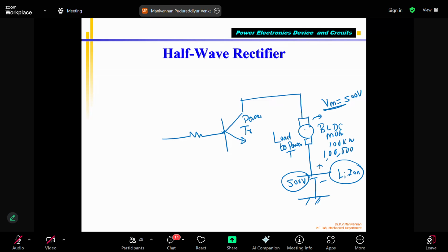coil has resistance, motor resistance, like an RM. The motor manufacturer says, for example, 0.1 ohms, 0.5 ohms, sorry, 0.05 ohms. Correct? RM can be 0.1 ohms or RM can be 0.05 ohms. Please remember, I'm talking about less than 1 ohm because the power I am talking about is 100 kilowatts.